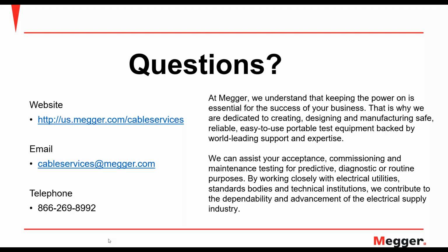In addition, if we review the IEC standard, it doesn't include a table like IEEE does, but it's for cables from 3 to 33 kV, and just mentions to test new cables at 3 times U0.